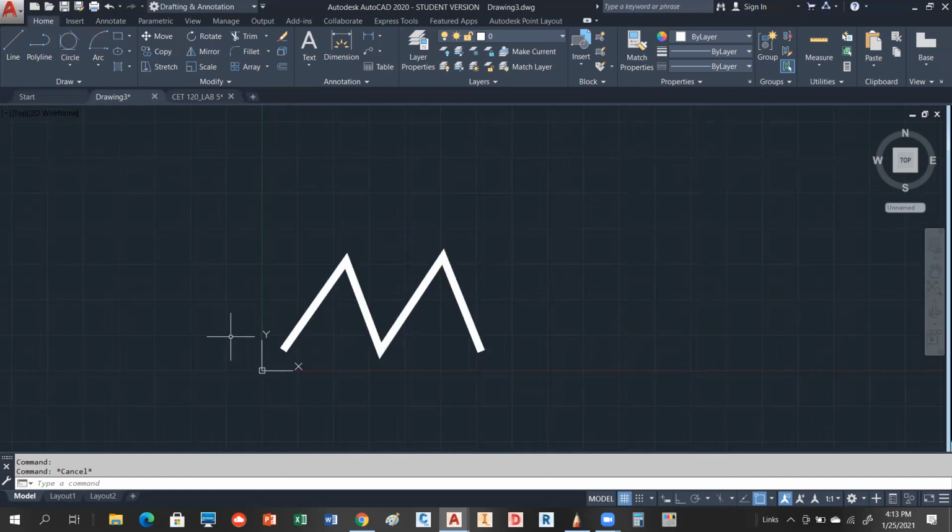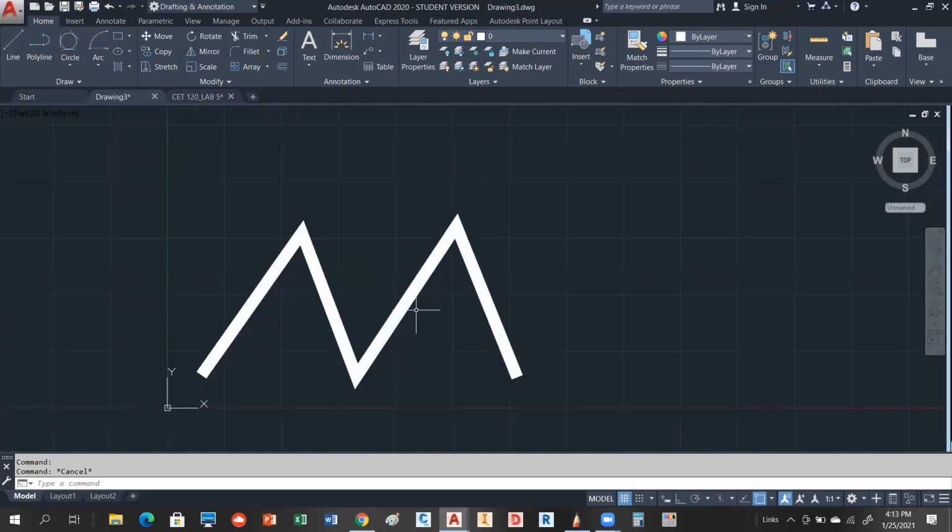One thing, by the way, is once you go into the polyline command and you turn a width on, it stays on. So if you don't want to have a polyline with width, what you would need to do is make sure as you're creating them, you set your width back to 0, and that would give you no width. I'm going to leave my widths on just so we can see them.